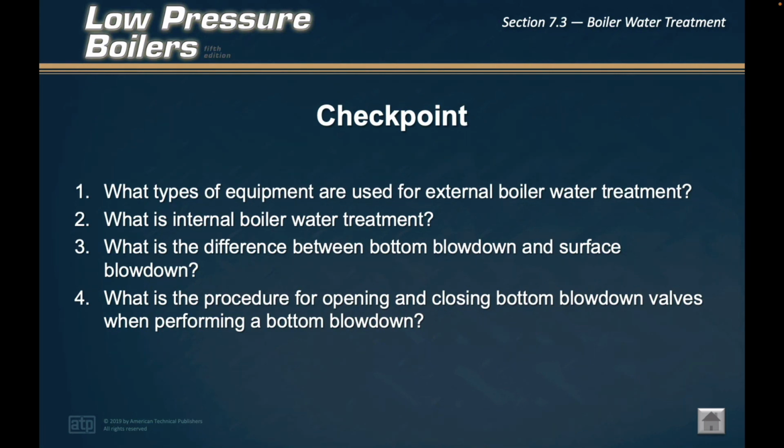That slow opening valve would be closed first, because remember, that slow opening valve is taking the brunt of the boiler water and the conditions, and that boiler water is beating against that slow opening valve. So you want to always ensure that valve furthest away from your boiler is taking the beating. So that slow opening valve is opened second, right?